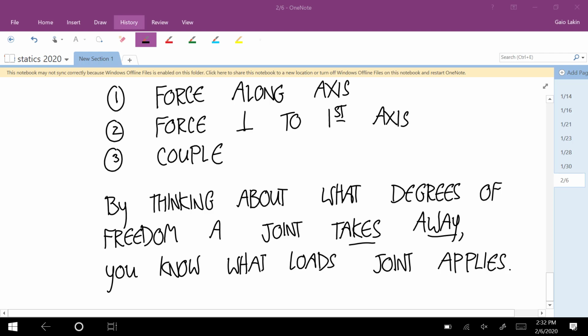So for example, of all the types of joints we're going to talk about, the last one is a fixed joint, or sometimes it's called a weld joint, but it just says the two objects are rigidly connected. With all of these, what you want to do is think about nothing acting on the object except that joint, and then think about how many degrees of freedom have been taken away from the 3 this thing would start with in outer space.